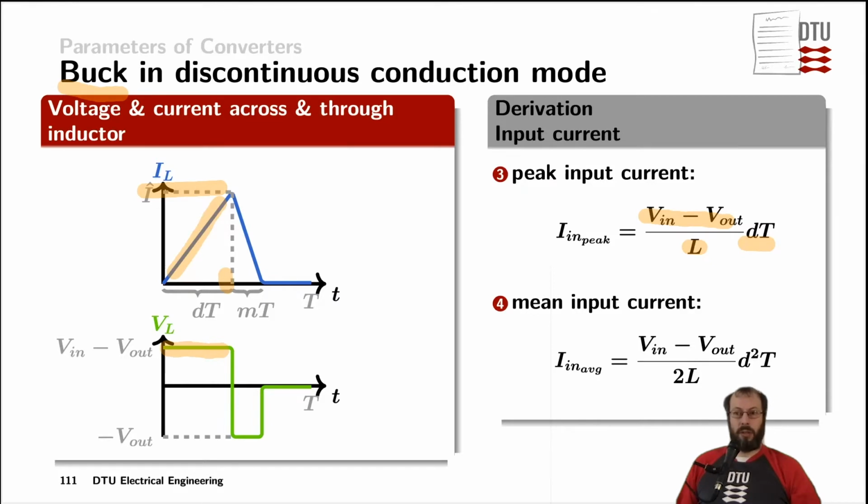Now, in terms of a buck converter, this triangle also represents the input current, as the switch is not conducting later on anymore and the input current is going back to zero. So the average of the input current is actually the area under this triangle averaged over the time period T. The area of a triangle is the height of the triangle, I peak, times the base of the triangle, which is D T, and then halving the result.